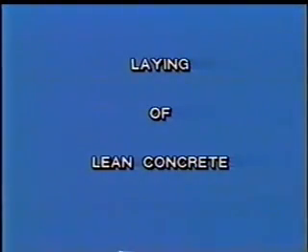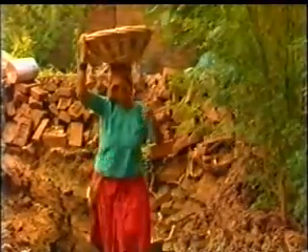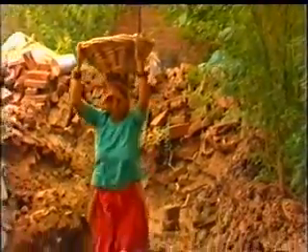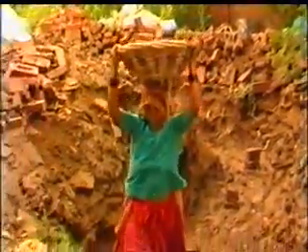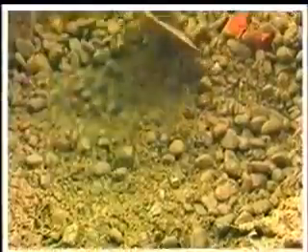Laying of lean concrete. Depending upon nature and intensity of loading, lean concrete layer of required thickness and proportions is laid in foundation trenches. The lean concrete mix is placed and compacted for obtaining level surface for foundation masonry.